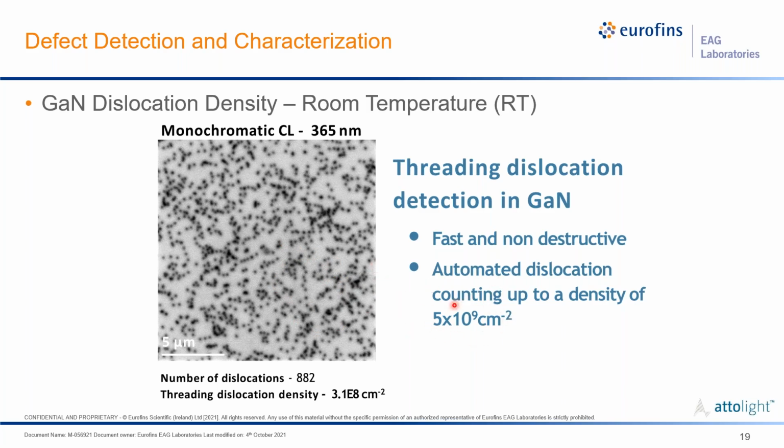So in cases where the defect density is higher than 5E9, then maybe something like ECCI, which is a SEM-based diffraction technique, that's kind of useful. And also TEM-based techniques are really good, but as you get to much lower defect densities, it becomes a problem. So you can do things like etching and imaging in SEM, for instance, or we can try SEM-CL, and in some cases it's very effective.